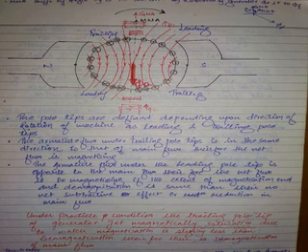If you see under the leading pole tips, the main flux and the armature flux are quite opposing in nature. Like in a differential compound generator, phi SH is in this manner, phi SE is in this manner. What is the net flux in the machine? Phi SH minus phi SE. Similar to that, when main flux comes like this and armature flux comes like this, what happens here? Demagnetization.